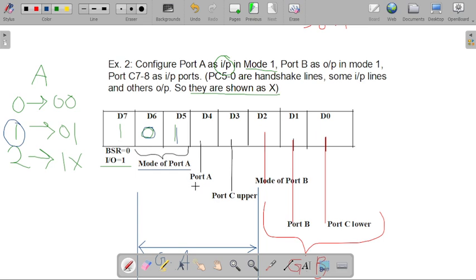Now the next bit is the port A structure. In case of port A, we are setting it as the input mode. For setting the data in our input mode, we have to set 1 in our control word format, and for setting the output, we have to write 0 in our control word format. In this structure we have to set the input mode, so I can write here 1 in case of the D4 bit.